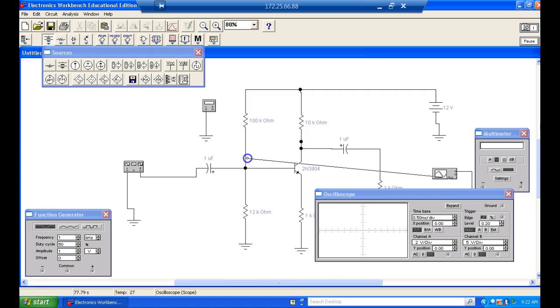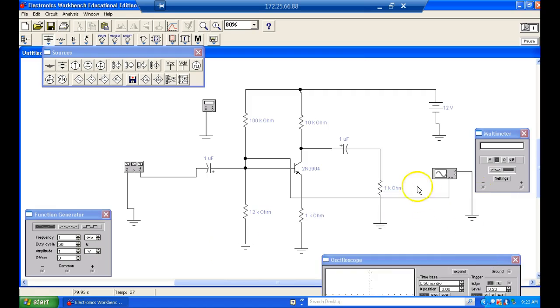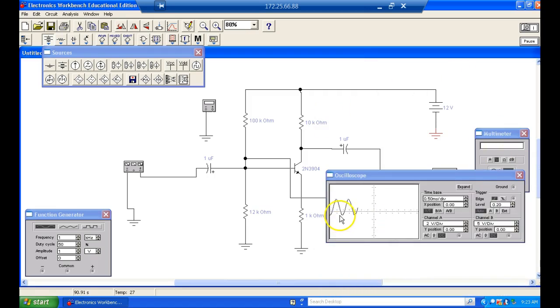So what would be the gain of this guy? The calculated gain. 10, right? So we take this guy and divide it into that, so we have a gain of 10. I'm bringing 2 volts in, gain of 10, 2 volts peak in, gain of 10, right? In fact, I'm probably bringing in more than that. Let's see, so I have it on 2 volts per division, so they're giving me 1 alternation. So I'm bringing about 4 volts peak in, so what would I try to get out?